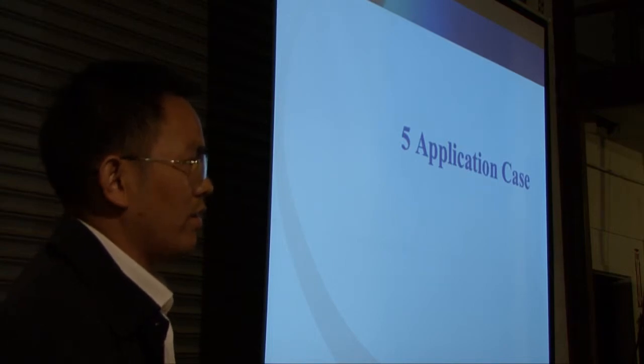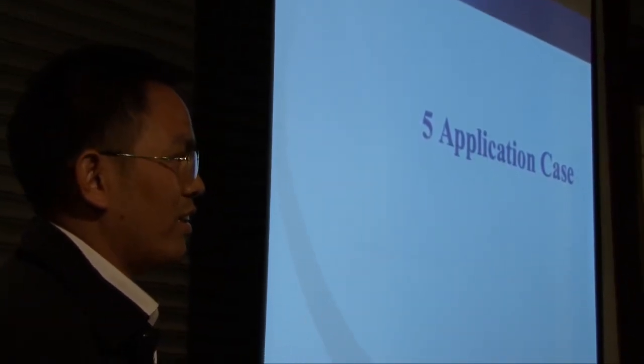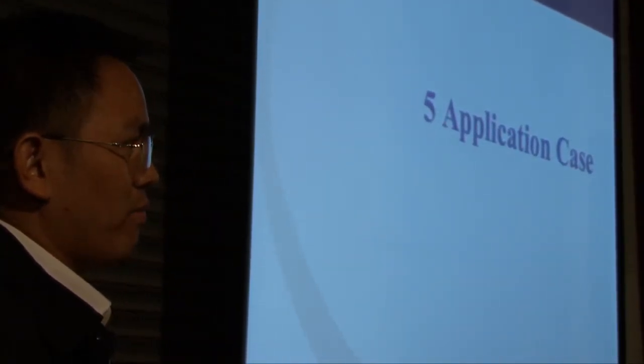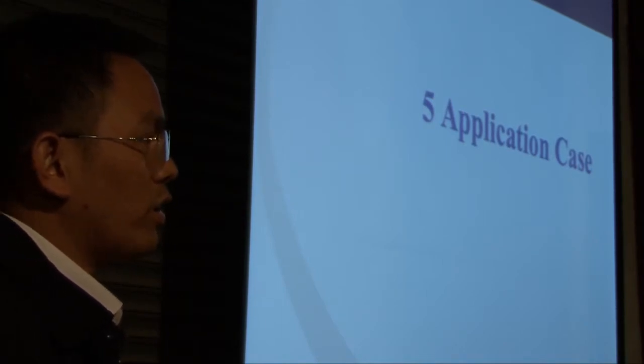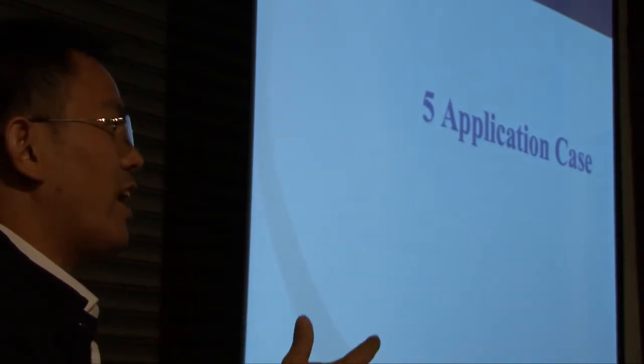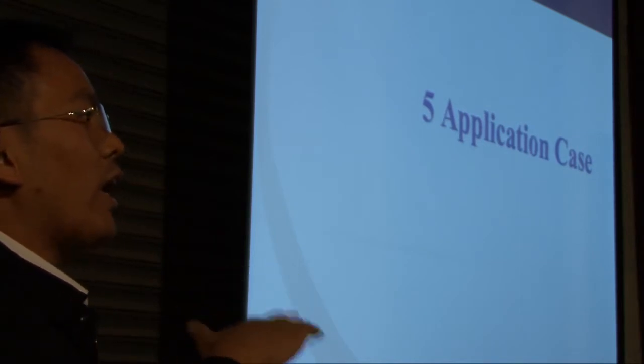So that's the basis of the question. I've assumed that the NDIR sensors are much more expensive, and when we bought them here, they have been much more. No, there are different kinds of NDIR. Now, a very simple NDIR can cost just maybe $40 or $50. It just depends on the accuracy. For industrial application, it may be more than that, because you should keep the temperature constant and use the infrared source with high accuracy and so on.